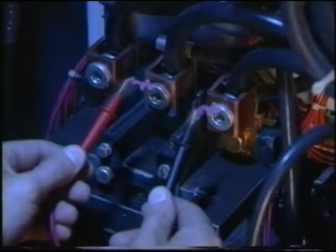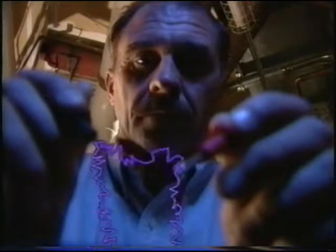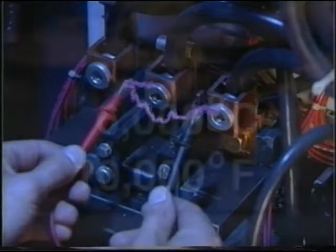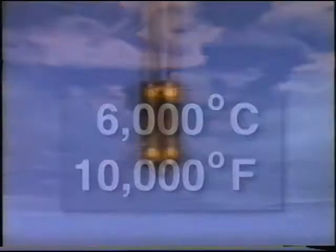If these two arcs join as the tech pulls away, one large arc is formed that provides a low-impedance path directly from one electrical phase to another. When two arcs join, they cause a phase-to-phase fault. The result is an arc blast. The energy in the electrical system can fuel a plasma fireball. Temperatures can reach about 6,000 degrees Celsius or 10,000 degrees Fahrenheit.